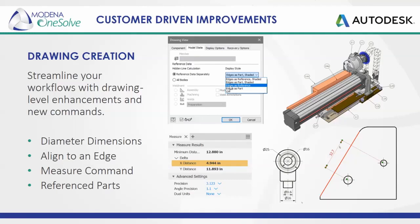Another new dimension tool that has been added is the ability to align a dimension with a reference edge selected from a drawing. The intuitive measuring tool that we are accustomed to using in the 3D modeling environment can now be used on drawing documents. Any component that has been set to a reference part to be used as construction geometry or add context to the design can now be manipulated using various display options. Here is a short video displaying these drawing functionalities.